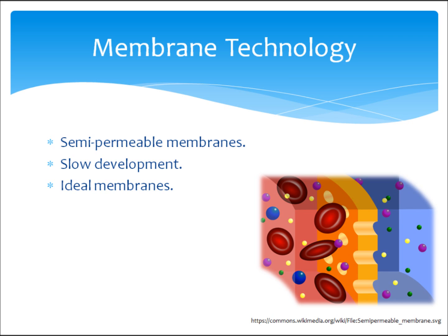The efficiency and high cost of membranes has been the main factor that has slowed down the development of osmotic power plants. The ideal membrane has high water permeability, low salt permeability, low attraction to fouling substances, and must be cost-effective and be able to withstand high pressure differential between fresh water and salt water. The thin film composite membrane, or TFC, has proven to be the most effective in reaching the goal of 5 watts per meter squared.